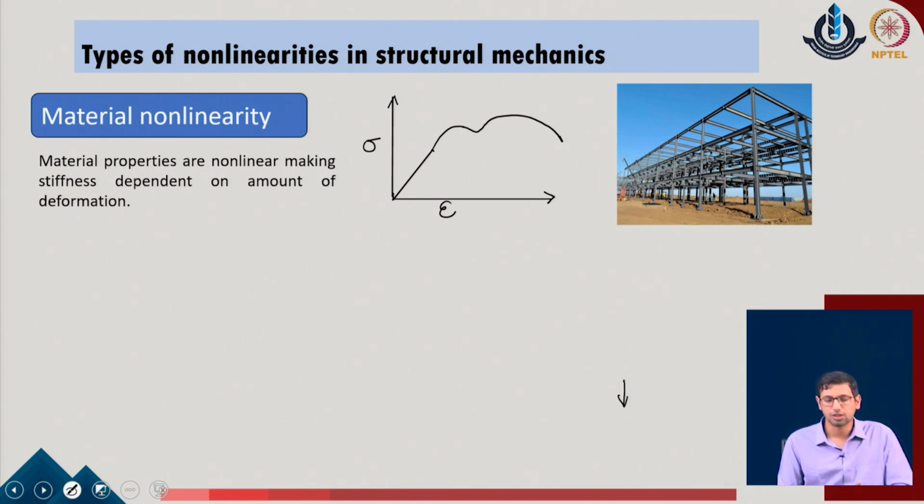Most of the time we have seen our stiffness relationships are a function of the elastic properties of the given system or the shear modulus of the given problem. Now, if the elastic properties of the given system are no longer linear, and they are also changing non-linearly with the increased value of the stress and the strain level in the given system, the user has to adopt the same non-linearity in the structural analysis framework as well.